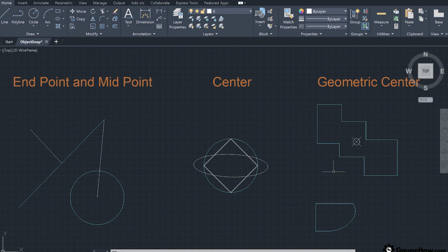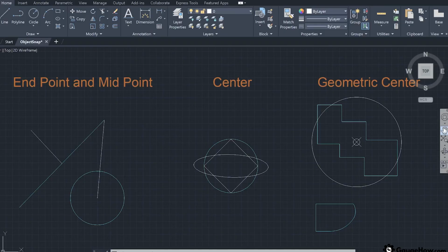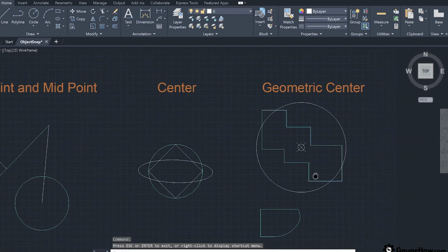Next, if I want to draw the circle at the center of this geometry, then to select this point, node snap is useful. So now I will select the circle option and move the cursor to that point, and you will see that that node is easily selected, and once I select it I can easily draw the circle of required radius. Now panning to the next available geometries to understand another tools.